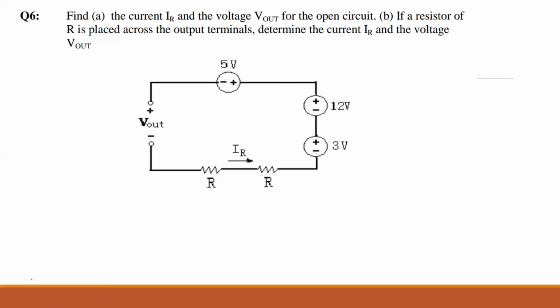In some cases, we have to assume the direction of current. If we assume the direction of current, we do the positives and the negatives according to that. But in this case, they have given us the current. So always for resistors, current is coming into the positive side because they are consuming energy. Okay, now the same thing.